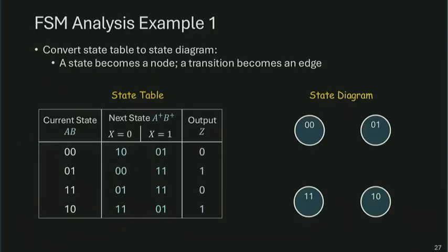And I promise you that through analysis, you can recover the state diagram. What I just showed you is a state table. But state table and state diagram are really equivalent representations. Conversion between these two is trivial. Every state, by definition, becomes one node in the graph. So you have 4 states, which translates to 4 nodes. And we need to add some additional transitions based on the input condition. So 0, 0 on the input of 0 goes to 1, 0. 0, 0 goes to 0, 1 on the input of 1. Oops.